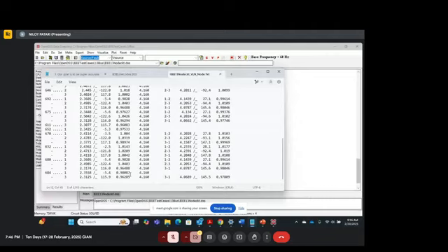Obviously, if you go into more detail, you can find standards where, under emergency conditions or under different conditions, it says how much voltage dip or voltage boost you can allow. You can find that online, but it will definitely be below 0.95. It will say that you can go below 0.92 or just stay above 0.9 per unit for this amount of time and all of that. Those are standards for power engineers, but just for your knowledge, for steady state, we try to keep bus voltages within that plus minus 5%.